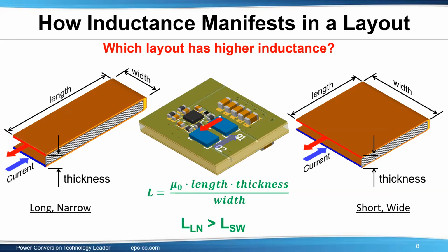Is it advisable to put CM chokes or PI type filter at the input of the gate driver? No, absolutely. The gate driver going to the gate must be as direct as possible. First of all, the driver has to have two outputs. These are the recommended gate drive for GaN FET: one output is to switch on, the other one is to switch off, and then having just a resistor.